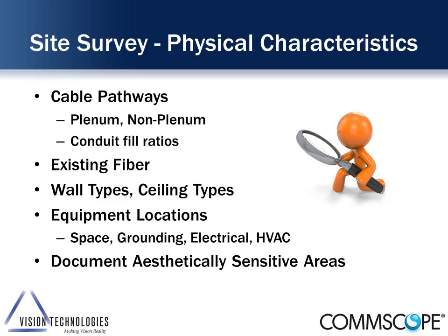Also inspecting the existing fiber the customer may have. Is that fiber usable for the DAS, or does new fiber have to be installed? So understanding the existing fiber, how it's terminated, where it's terminated, are critical pieces to developing and designing an overall solution.